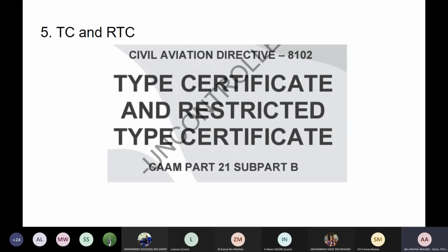Those are airworthiness requirements. And you don't see a drone there. You don't see any LSAs there. You see only aeroplane, large aeroplane, small aeroplane, helicopters, engine, propeller. So it means that other than that, it's not eligible for the standard certificate of airworthiness. Some countries do issue a special airworthiness certificate, so still they do not get a full COA for non-ICAO Annex 8 aircraft. We call it ICAO Annex 8 aircraft when the aircraft design requirement is according to ICAO Annex 8, or in Malaysia now, it is CAT 8.